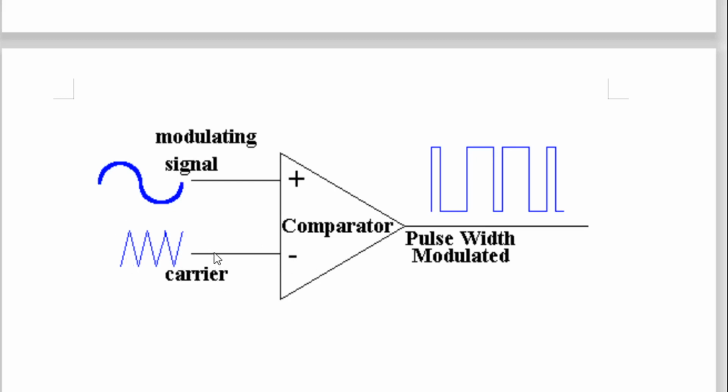And as I told you, in pulse width modulation our carrier signal is a triangular wave. The carrier is not a square wave. The square wave is what we are going to generate, and we are going to generate this square wave such that the width of the pulse, meaning the width of the square wave, changes, because our modulation name is what?